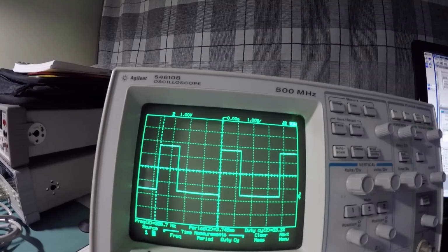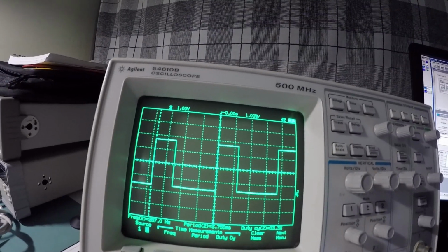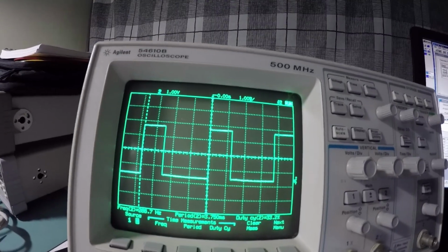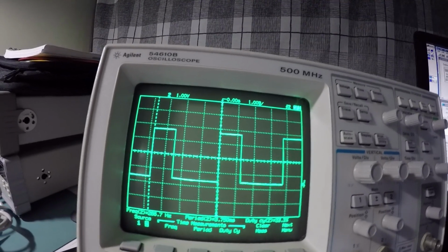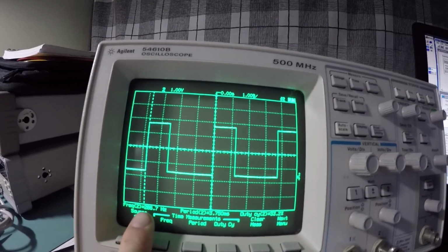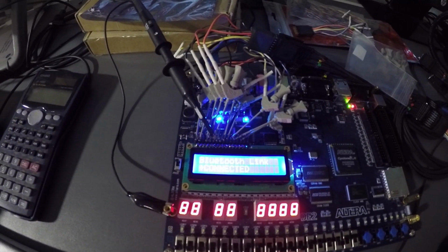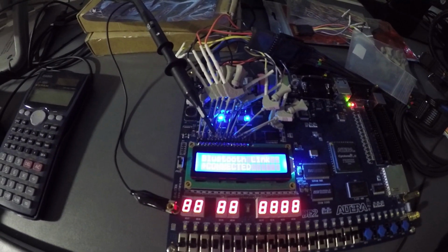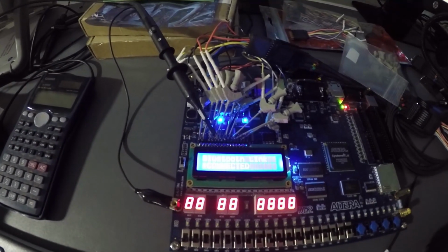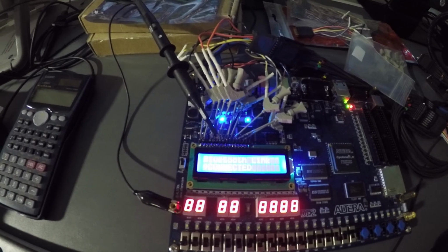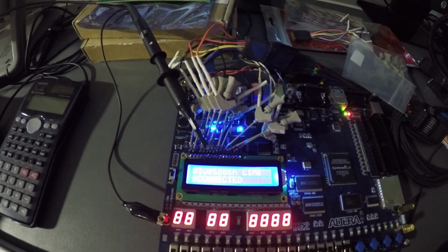And so by removing that hold state that I had added, I was able to put it back to its original condition, and the frequency on the LCD enable came up to match the variable name that they had chosen to call that particular clock pulse at 400 hertz. The fact that they chose to call it 400 hertz when technically it was not just confused the heck out of everybody.